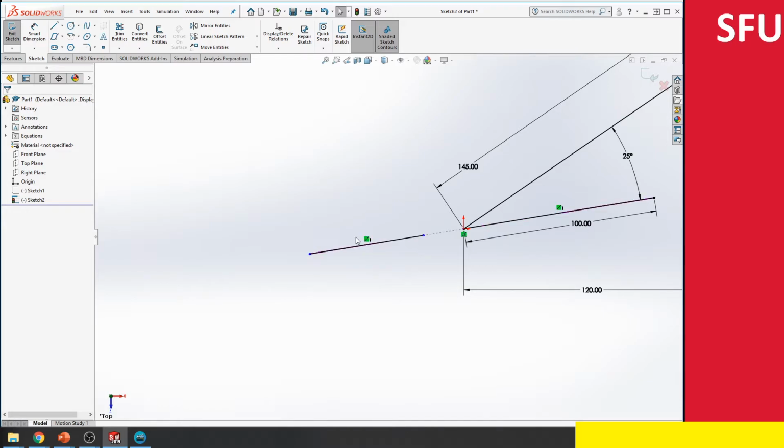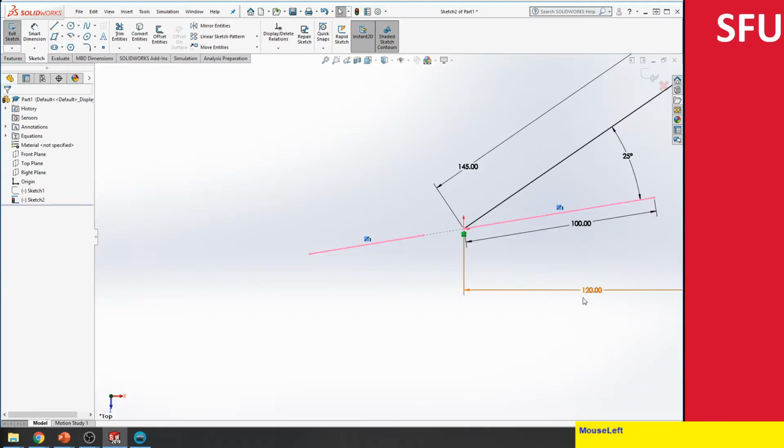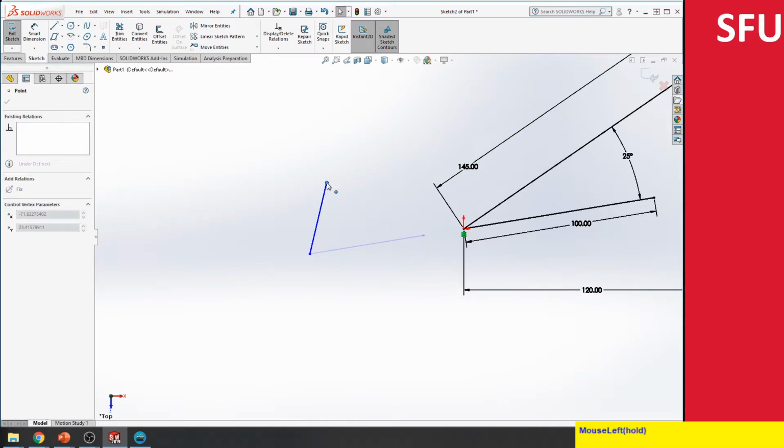It also has a number associated with it. And so this is basically saying you set a collinear constraint between this line and this line. Notice that I can't really move this line. Instead, if I click on this box and then hit delete, I've actually deleted the constraint, and now I'm free to move this point any which way I want.